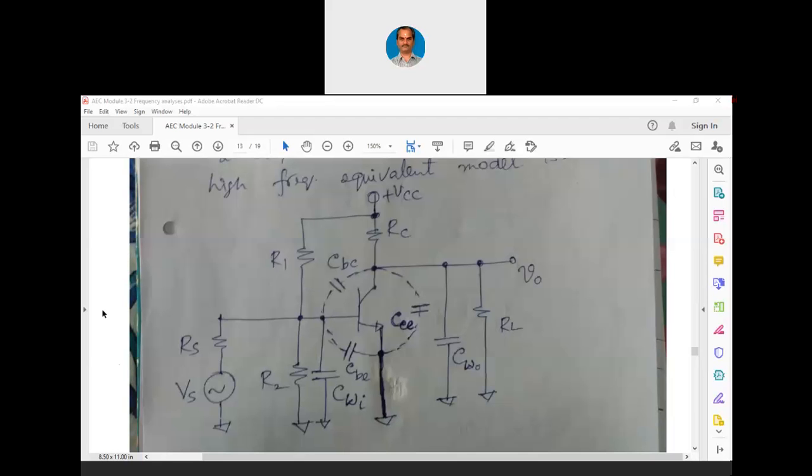In between the main wire and the ground wire, there is always a capacitance, because all wires will have insulating sheaths. All wires which we use are protected by an insulating plastic sheath. That plastic sheath is acting like a dielectric medium. Even inside integrated circuits, we have insulators in between two metal layers, so there also the capacitive effect is there. So wherever there is a wire, there is a capacitance. From the input side, if we model that wire, we have to write a capacitance with respect to ground. Similarly, at the output also, we will have to model that with respect to ground.